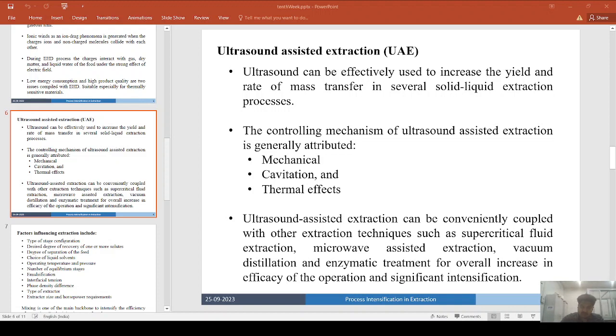The ultrasound assisted dynamic extraction may result in the highest yield because the extraction proceeds all the time with the flowing solvent, having therefore a better mass transfer and better contact between solvent and solid. The combination of ultrasound and enzyme treatment may increase extraction yield with short treatment time, so therefore more research is required.